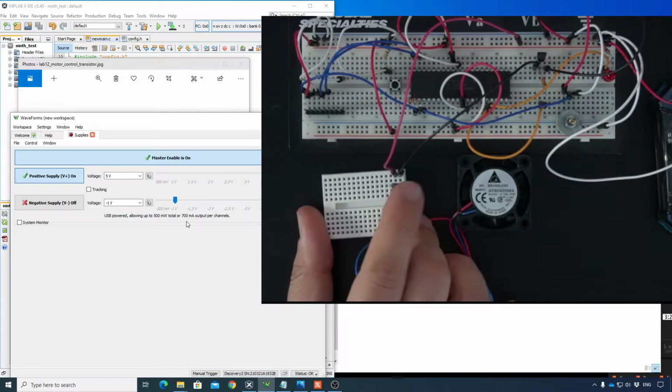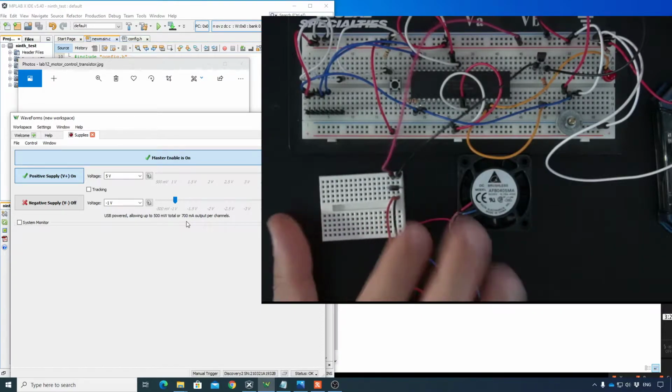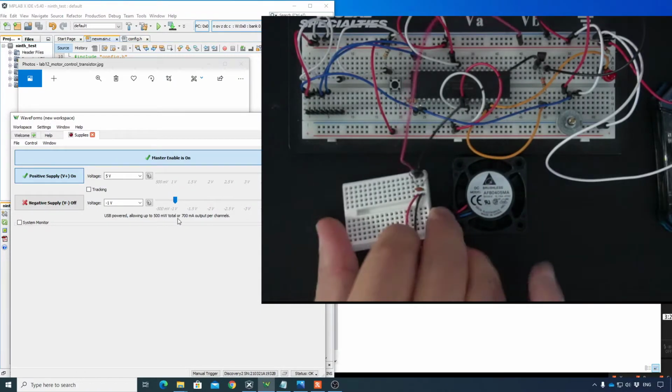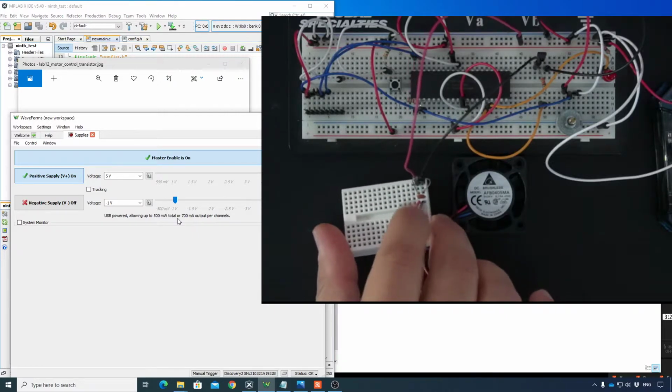Okay, so you do see the LED here, but what happened is whenever I turned it on, every now and then, whenever this motor just starts, the voltage spikes a little bit, and because the voltage spikes and the current spikes as well, my protection in this power supply just turns off because it exceeds the limit. So my solution was I connected a capacitor in parallel.